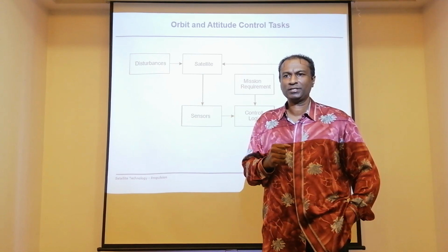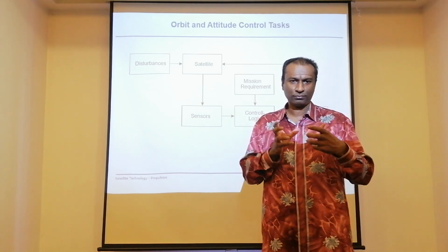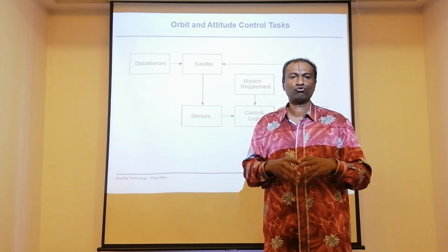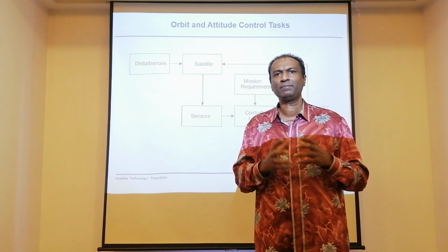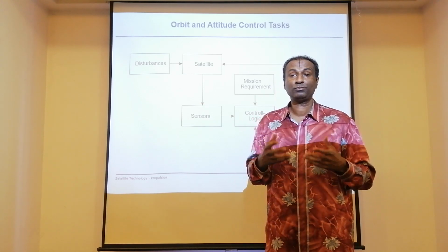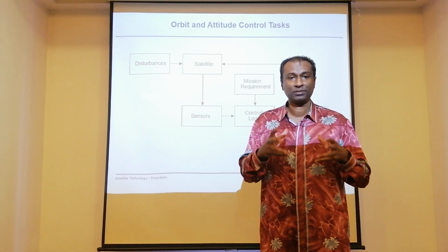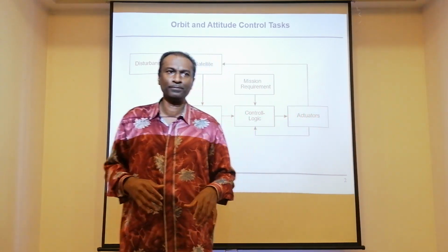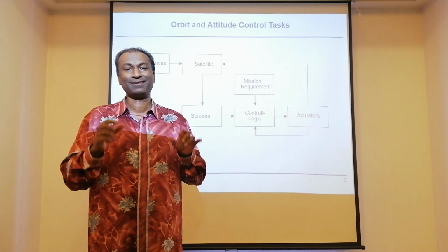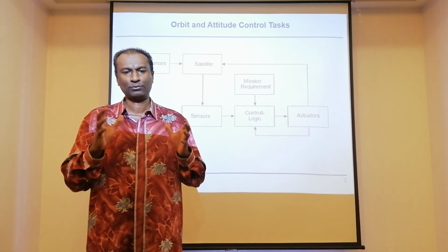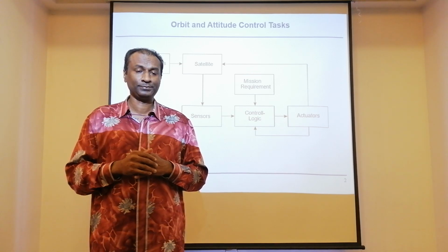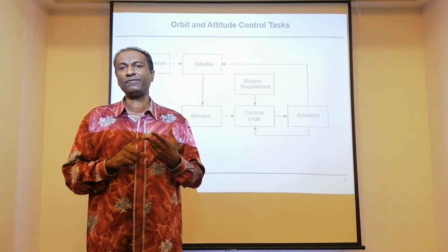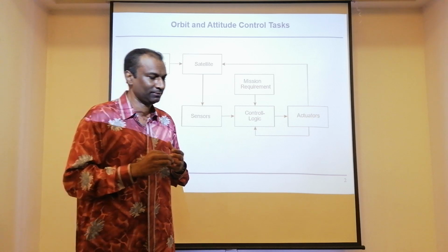Now, in chapter 3, we treated the rotational motion with devices such as reaction wheel, momentum wheel, control moment gyro, even the spin stabilized technique. That provides us with the rotational motion. But there is a system, the propulsion system, where the way we mount the propulsion system, or the thrusters, in our satellite can give us either rotational motion or translational motion, or both motions. That is important to understand.